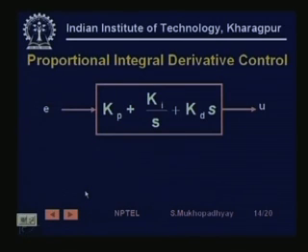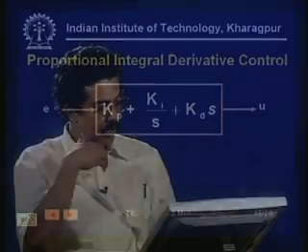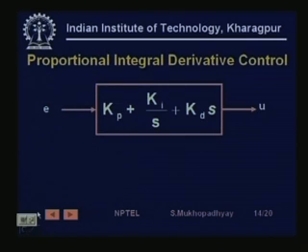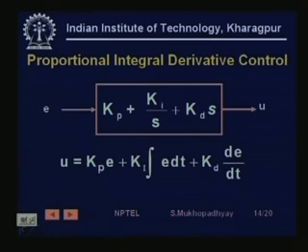We have already discussed proportional and integral controllers, and we have also seen that adding a derivative will try to brake so that it does not go towards much overshoot. So, we need a proportional controller, because if you do not have one, there will tend to be too much oscillation. We need an integral controller to have 0 steady state error, and a derivative controller to have low overshoot and fast settling time. We need to tune these gains Kp, Ki and Kd nicely, so that we get a good transient response without sacrificing the 0 steady state error.